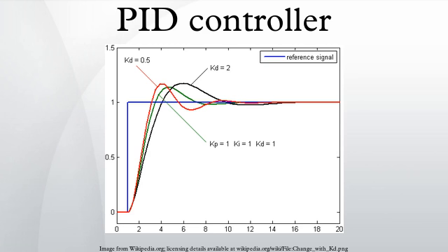For example, a temperature-controlled circulating bath has two PID controllers in cascade, each with its own thermocouple temperature sensor. The outer controller controls the temperature of the water using a thermocouple located far from the heater where it accurately reads the temperature of the bulk of the water. The error term of this PID controller is the difference between the desired bath temperature and measured temperature. Instead of controlling the heater directly, the outer PID controller sets a heater temperature goal for the inner PID controller.